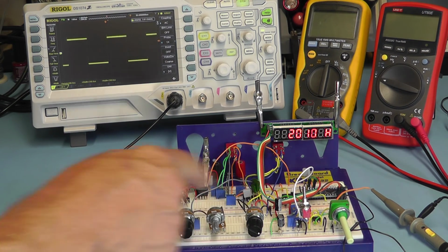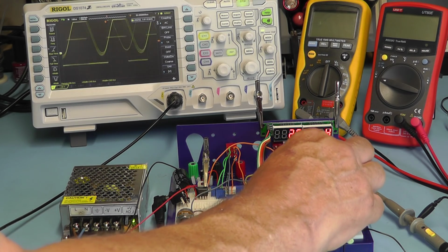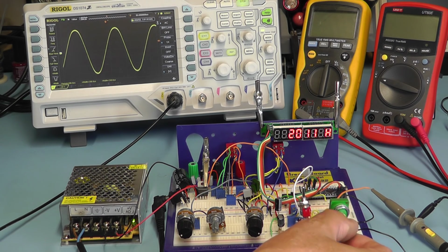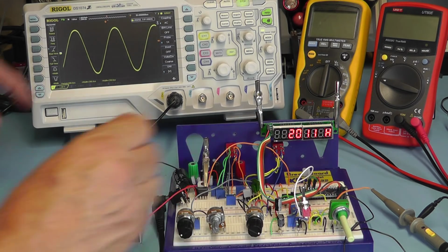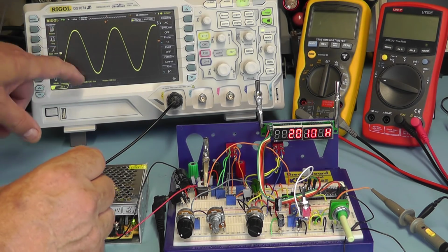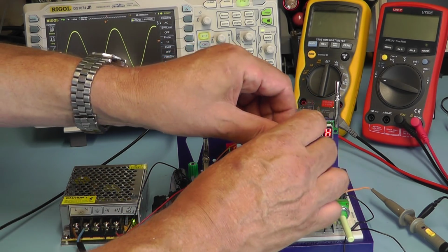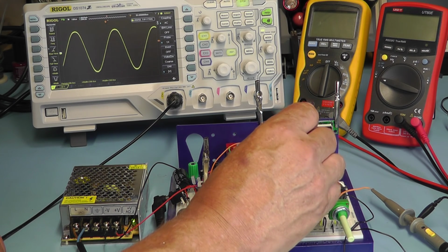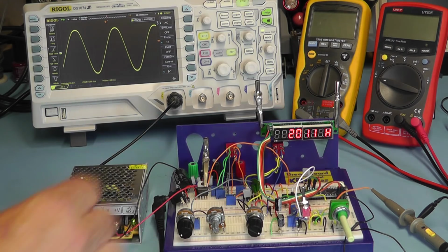Right, I'm now going to check the output signal levels for this output stage. What we'll do, we'll switch it to the sine wave first of all, and set the output gain control potentiometer there to maximum, and I'm just going to trim the preset so we have, in fact it's just more or less there actually, but that's basically trimming the preset there to give us a 6 volt peak to peak sine wave signal coming out, which is there.